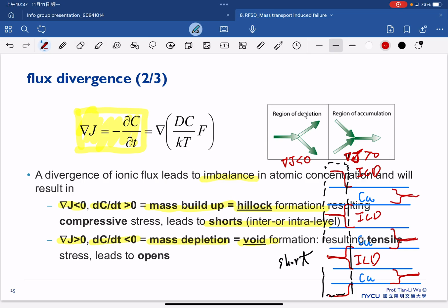And this void formation clearly happens because your interconnection line is completely gone in this region. So you actually try to open one place to another, so carriers cannot easily flow, and this causes the open.